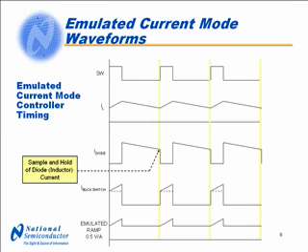Shown on this slide is a timing diagram for the buck regulator power stage. You can see how the inductor current is the sum of the buck switch current and the diode currents. The sample and hold is accomplished at the times indicated by the yellow bars. This sample and hold establishes the pedestal level. Shown on the bottom is the emulated ramp signal, which in this case is scaled to 0.5 volts per amp.